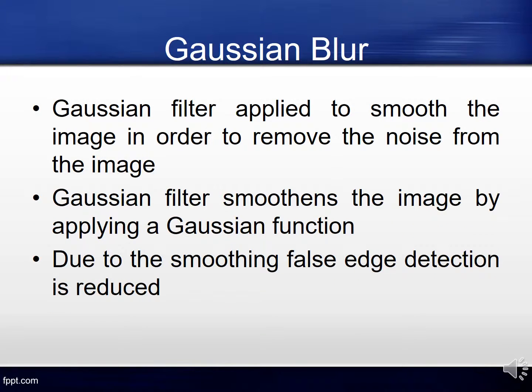The RGB video feed is received from the camera. This is first converted into grayscale. Before applying the Hough transform or Canny edge detection algorithms, it is necessary to smoothen the image to remove noise. The primary purpose of using the Gaussian filter is to reduce the detection of false positives. A Gaussian filter blurs or smoothens the image by using a Gaussian function.